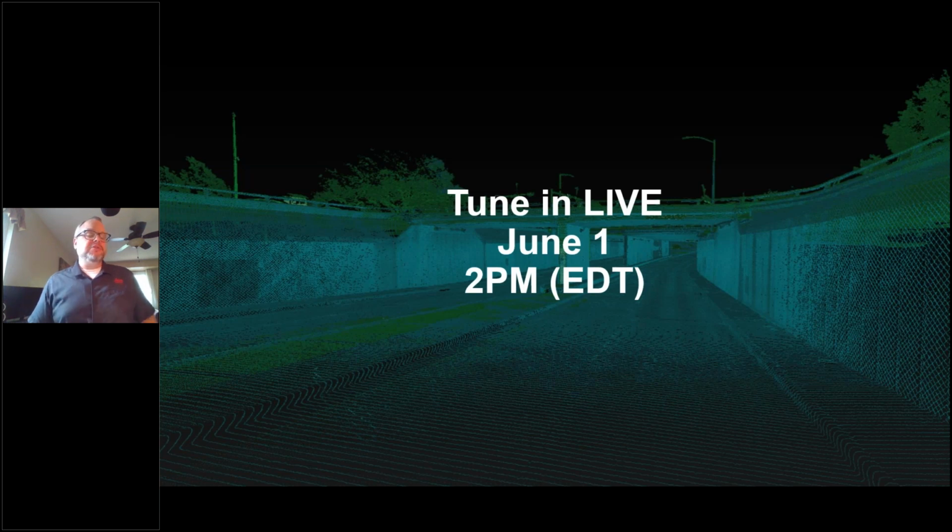If I'm using Inertial Explorer to analyze the quality, I'll look at the estimated positional accuracy. So that's the first plot that I would look at. I would look at the combined separation. This is telling us how close our forward in time and our reverse in time trajectory solutions match one another. I would look at those two. I would look at satellite bar. I would look at the GPS and IMU positional misclosure. So these are all handy plots.